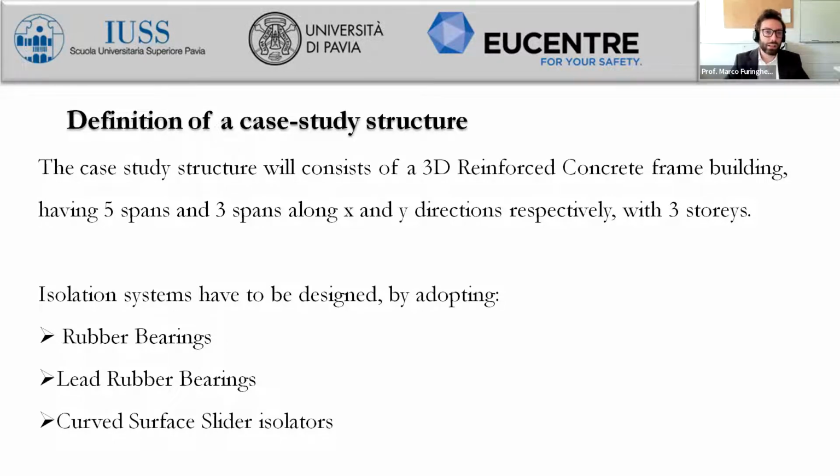So the special links, which provide actually the proper modeling assumption, so the theoretical response for such devices. And the special link is needed because the lateral force of the device is directly a function of the applied vertical load to the device itself.